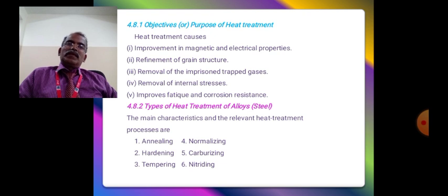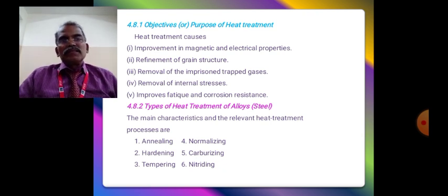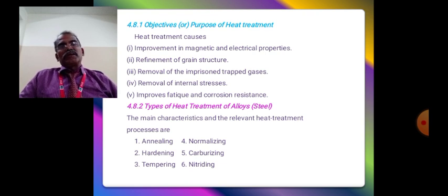What are the objectives? This heat treatment causes improvement in magnetic and electrical properties, refinement of grain structure, removal of imprisoned trapped gases, and removal of internal stresses of steel.